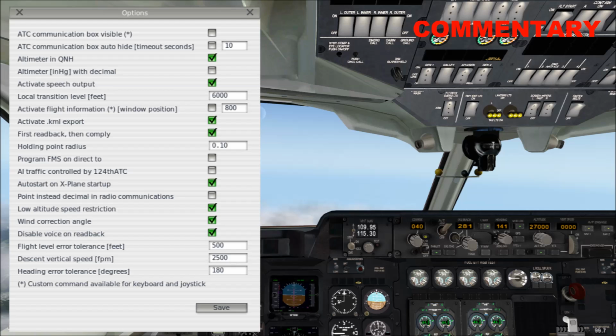With the heading error tolerance, you can set at which heading deviation ADC will provide correcting heading information. As mentioned earlier in this video, in the current version the plugin is giving too many heading instructions. For this reason I set the value to 180 degrees, practically disabling all heading instructions. In future versions this will be improved and the setting can be changed down to, let's say, 5 degrees.